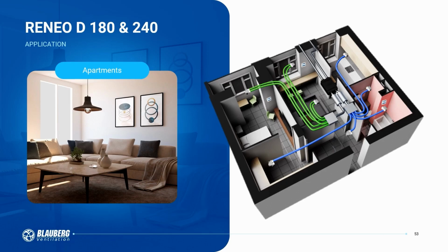The system can be additionally equipped with a humidity sensor in the bathroom and a CO2 sensor in living areas. If the apartment includes a smoking area, the unit can monitor air quality using a VOC sensor. To prevent allergic reactions, it is recommended to monitor particulate matter levels, PM 2.5, in the air.